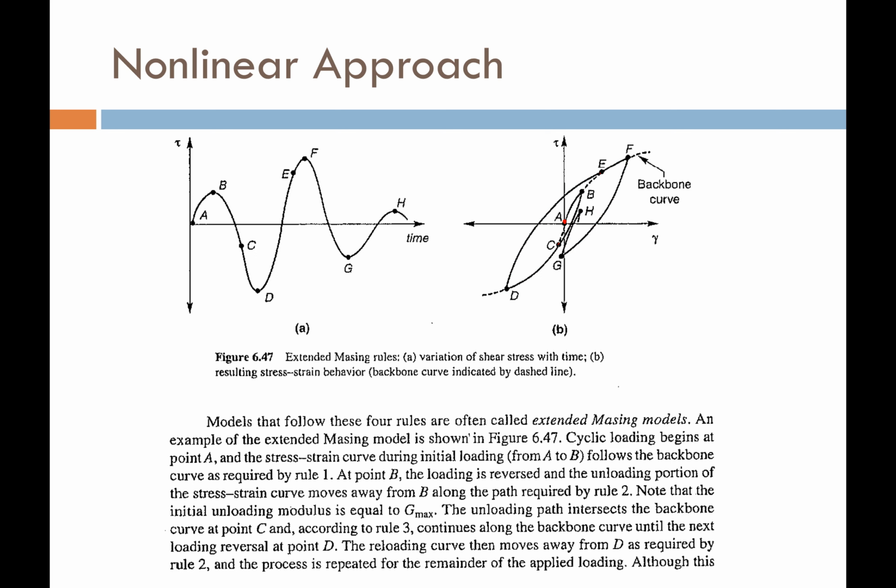And so a particular constitutive model may follow the old Masing criteria, but understand that there's like a dozen or more modifications of the Masing criteria that are all based on laboratory testing, or I should say they're usually based on laboratory testing and then applied to numerical modeling.